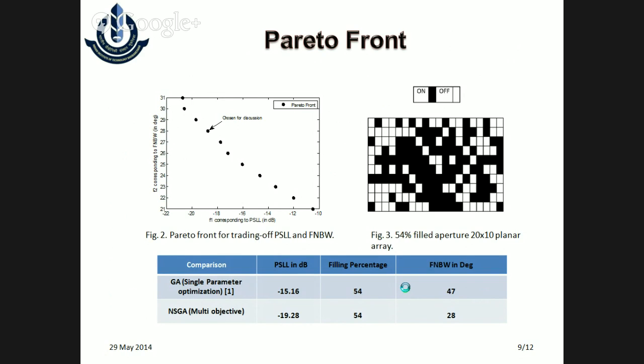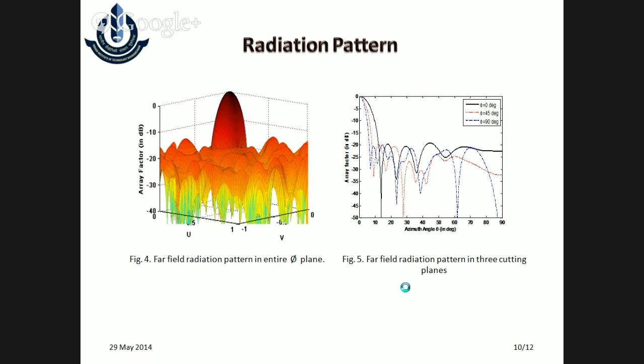Like that, this is the radiation pattern. This is the radiation pattern in all planes. We are representing up to 0 to 90 degrees planes. At the same time, we are taking the Cartesian format at 3 different planes. We are maintaining 19 decibel side lobe levels, like that.